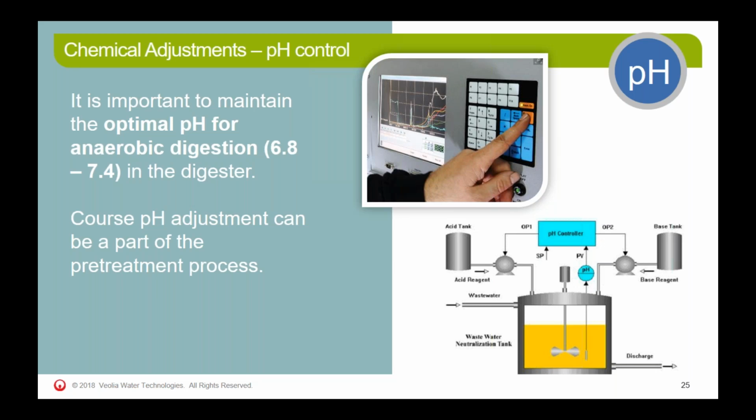So applying some volumetric equalization of the pH, where we combine streams at different pHs that would self-neutralize, or we provide a neutralization system where we have an expansion in line where we can add additional chemistry to neutralize pH. It would aid with the processes downstream, be it the solid separation or the biological process. Next slide, please.